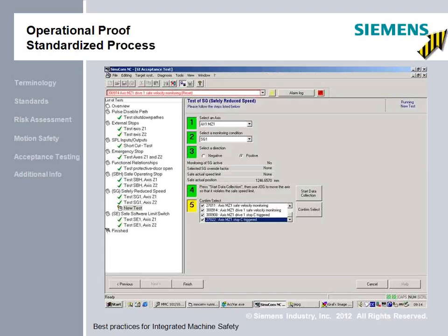Functionally, we do the same thing with the safety system, but because the safety system is more complex and is typically integrated, we have to have some more complex measures and maybe some higher level functionality from the control system to do our functional tests. In Siemens' case, the Sinumerik NC engineering tool for the safety CNC is what I'm showing here. This is actually a very excellent tool.